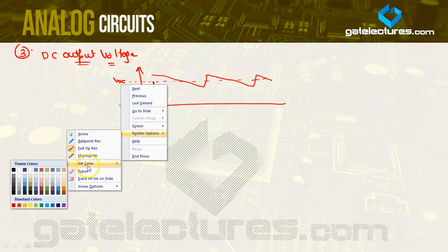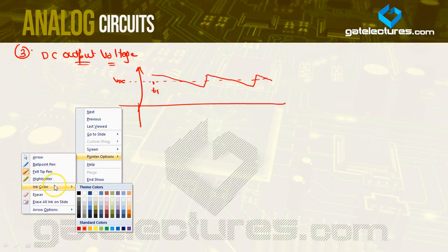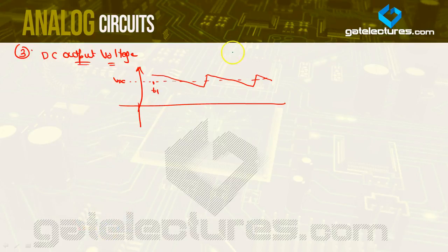Now if you observe it keenly, this amplitude is basically your Vm, and this is Vm minus Vr, as we already saw when we started our discussion on the half wave rectifier with the capacitive filter. So this is VDC and this is Vm minus Vr. What is VDC?